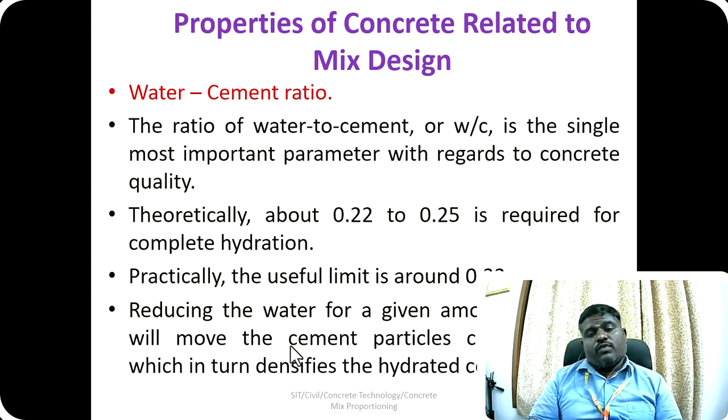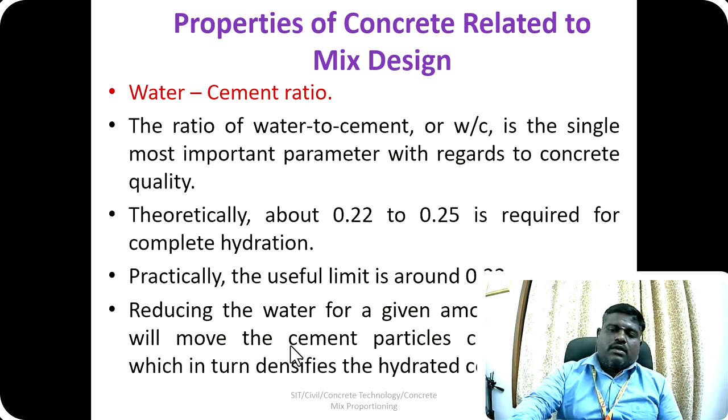If we increase the water for a given amount of cement, then the cement particles will not move closer to each other, and it will not make a densified hydrated cement paste, which will lead to inferior quality of cement paste.